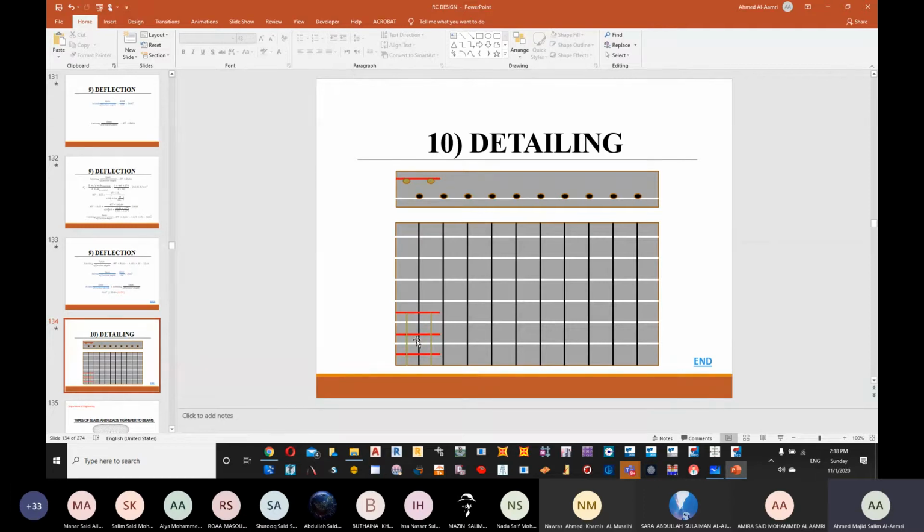Now, if you remember, this is my slab. For my slab, this was disconnected, and there was a certain portion where it's connected. So in this scenario, what you can see, I'll only supply the X negative reinforcement where it's connected. You can see that this portion was a portion where it's connected only. In the portions where there is no other slab, it does not need to be connected.